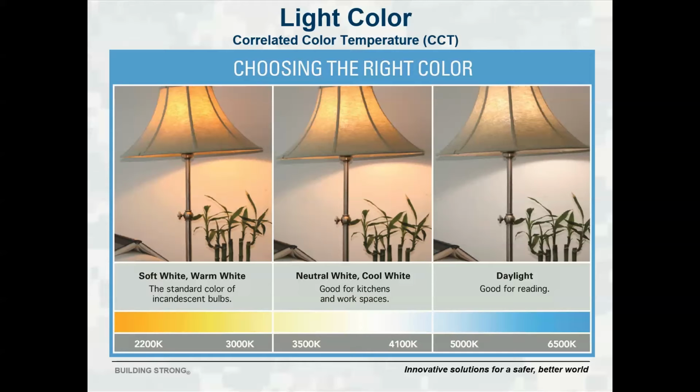These terms, from warm light to daylight, are standard terms in the industry that are used to describe different portions of the CCT spectrum. Most incandescent and halogen lighting falls on the far left side of the spectrum, in the warm white and soft white regions, but compact fluorescent and LED lamps can be selected in any of the regions. Generally speaking, many people strongly dislike working in areas with lighting on either extreme of the CCT spectrum. Providing light in the 3500 to 4100 K region usually results in the highest overall satisfaction.